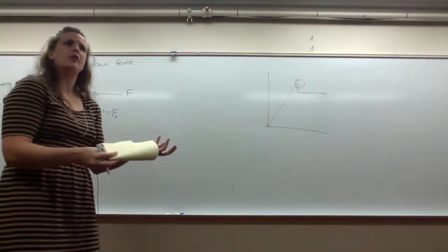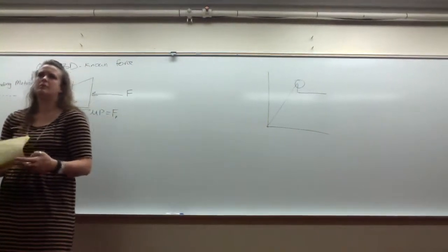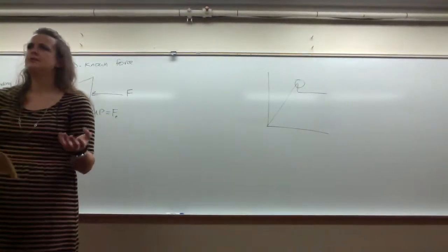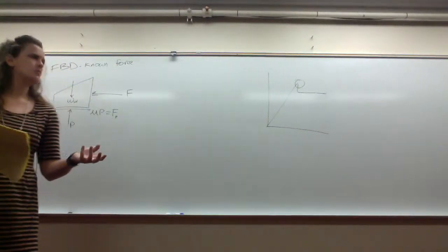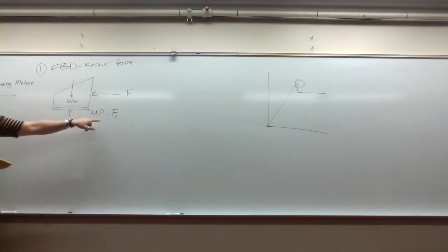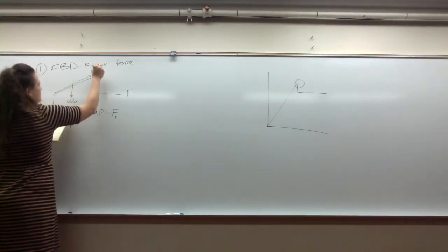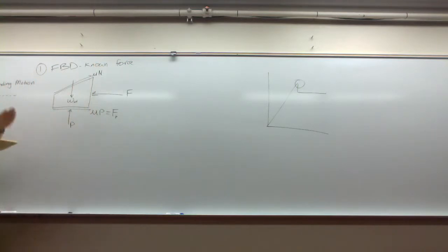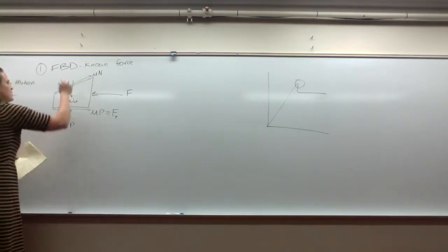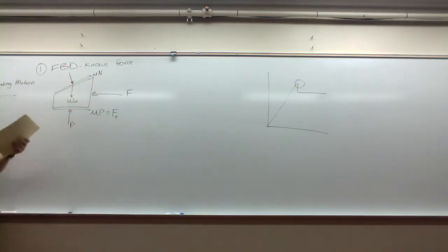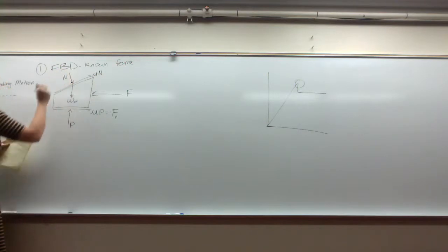Did you all pick up on that in your homework? When you're solving it and you apply your equations of equilibrium and you see you have 6 unknowns? Well, you don't really, because the friction force at p shares that normal force. All right? So we also have a friction force on the surface of the inclined plane, and it's opposing motion. So I will draw it up and to the right, and we have a normal force from the weight of the load onto the wedge.